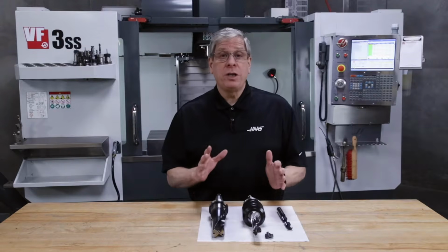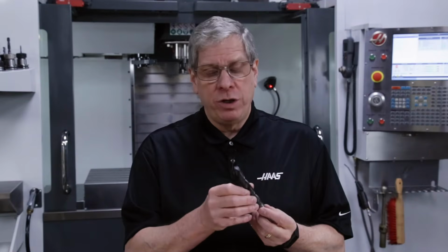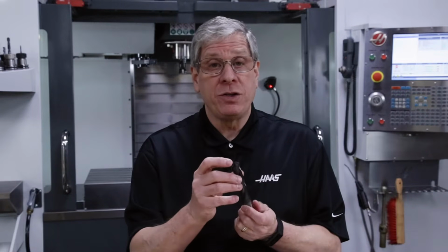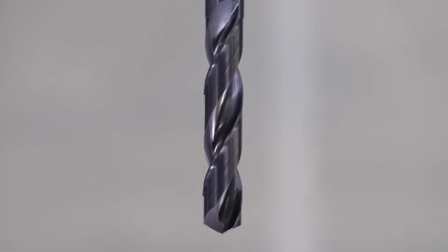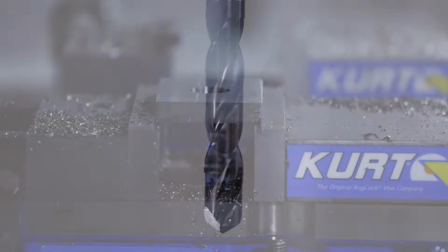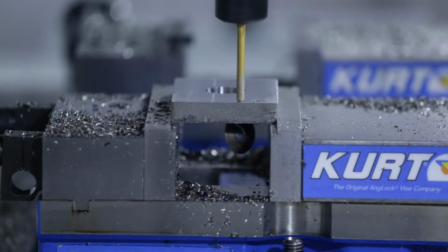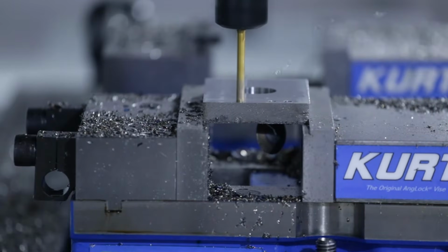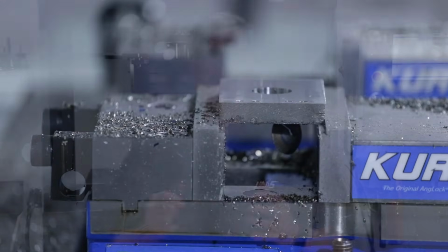Arguably, the most common cutting tool used in manufacturing is a drill bit. Now, I assume everyone knows that a drill bit has two cutting edges and rotates on its center axis. As it's fed into the material, the rotating motion provides continuous cutting action. The material that's cut, referred to as chips, are forced up these flutes and out of the hole. It's a relatively simple process that works very well. Drill bits come in a massive number of different sizes, so precision holes can be drilled to almost any specification.